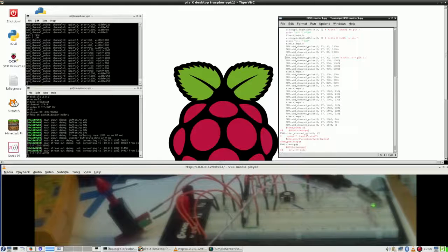So, right here, the necessary connection to the mass, to the ground, a multimeter set to voltage, measurement 20 volts maximum, and this probe should be in here, so I better hold it, and let's wait for the stream to catch up.